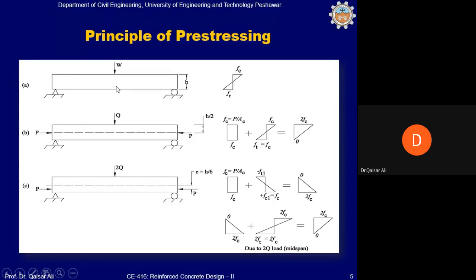And if you draw the stress variation through the depth of the beam, you can do this using the flexure stress formula as long as the beam is in the linear elastic range. f = My/I is the flexure stress formula. It will give you flexure stresses at any depth from the neutral axis, top and bottom. Flexure stress at the neutral axis will be 0, because y is the distance from the neutral axis, so when y is 0, f will also be 0.